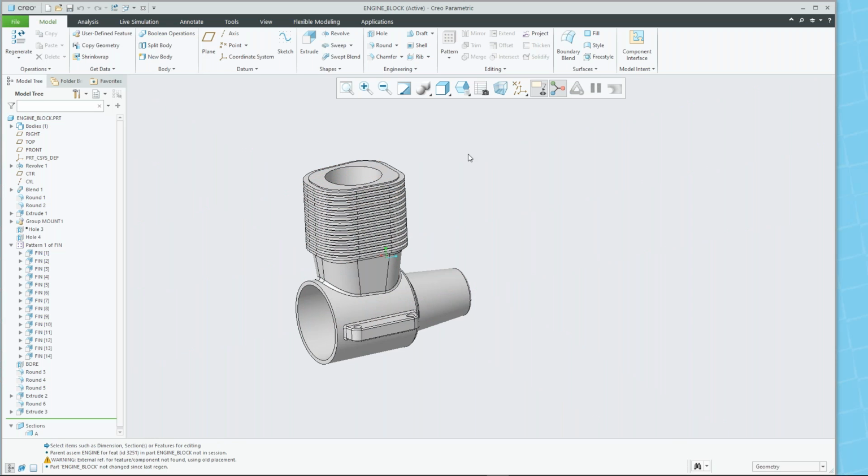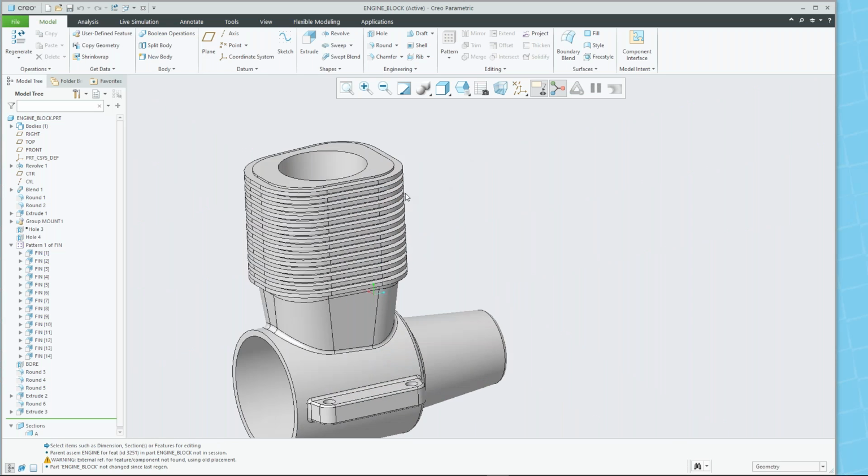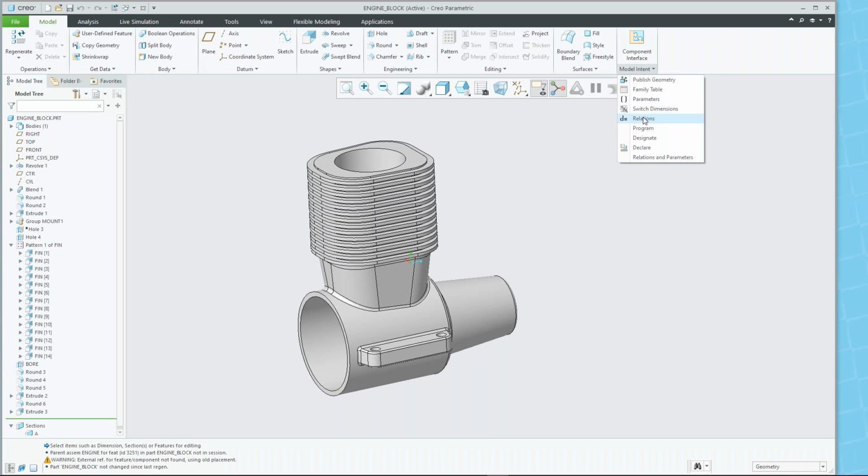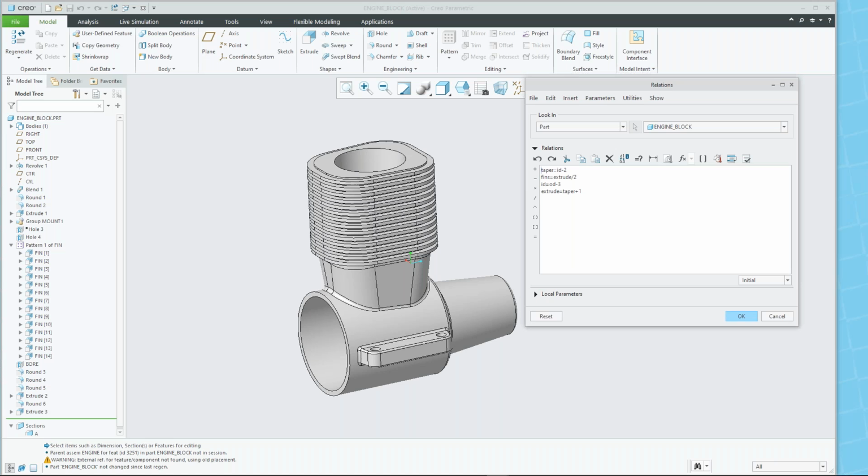But if you're noticing, it is having to regenerate this model twice in order to update the last part of it, which is the number of fins, because of the order that I've created everything. So I'm saying taper is equal to ID, then I'm saying fins is equal to extrude, and then down here I'm setting ID equal to OD. And then also down here I'm setting what the extrude is equal to, which is controlling the number of fins.